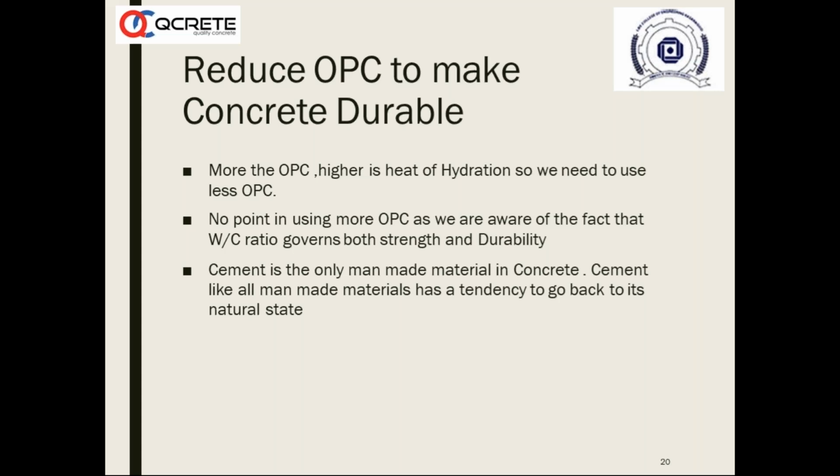How can we reduce the heat buildup? Heat buildup in a body of concrete can be reduced during the initial phases, while the hydration process is taking place. At that point, it can be controlled by using ice flakes or cold water during the manufacturing of concrete, and then by using supplementary cementitious material. So the first point is that higher OPC cement content is deleterious, or detrimental, to the longevity of concrete as it produces thermal cracks.